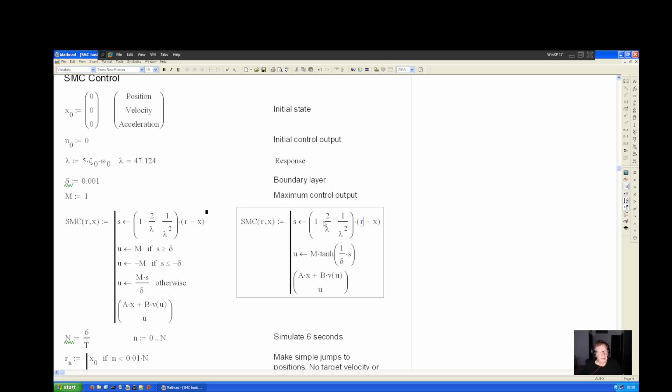And these are the weightings, and they're time constants, but basically it's like having the time constant times S plus 1, squared. This is the output. Anyway, this will ensure that I don't have overshoot. This is the state space calculation with the nonlinear valve calculation, and then this is the control output.